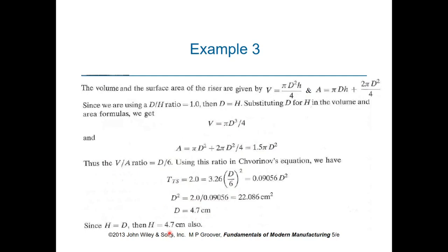So the required riser, in order to perform its function, is 4.7 centimeters in height and also in diameter. Its solidification time is 2 minutes, which is more than 1.6 minutes, which is for the actual product. So it has a longer solidification time, so it can perform its function properly. Okay. Are there any questions on this? No questions? Okay, let's move on now